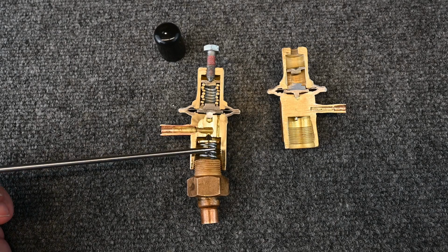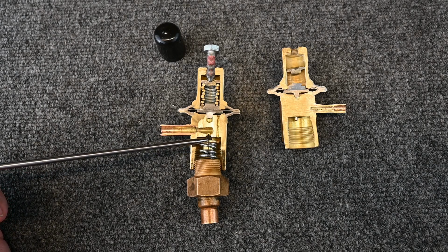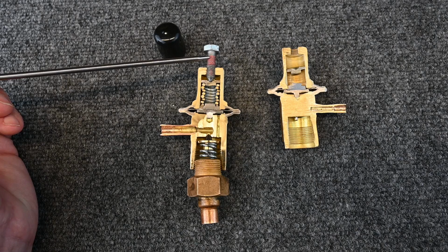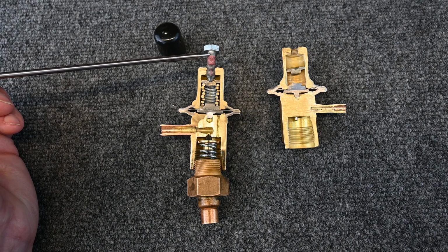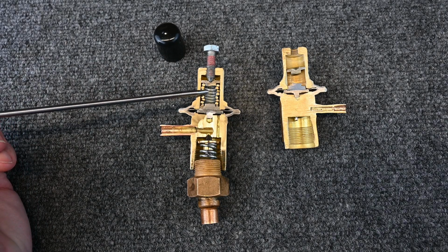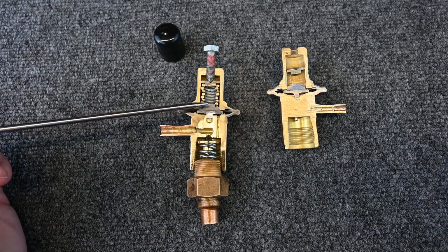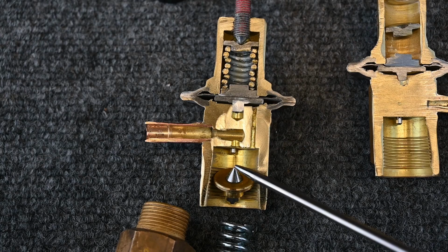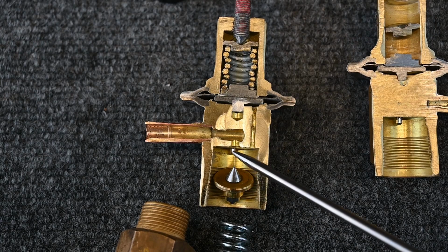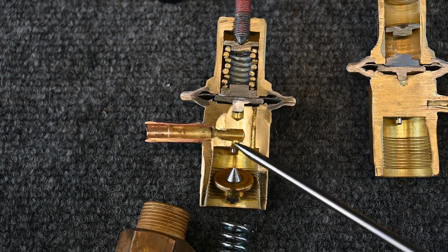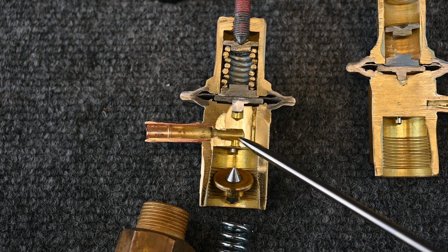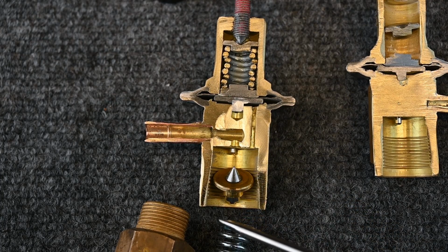Now if you notice, there's a spring here pushing up on this piece. We have another spring on the top side with an adjustment screw. So when we adjust it, we're really just adjusting the pressure against this spring, which goes against all these pieces here. Now, we've got to get the tension from here back to this spot. So right here we can see this cone shape. That cone shape fits into this little groove, or this little hole right here. With this cone out of the way, the refrigerant flows straight through here, through this hole into the suction side.